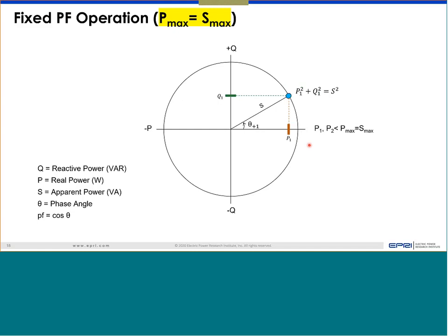If a further command comes, initially 0.97, now 0.92, then it has to go even lower, so real power has to go further down. So by having a power factor function, or a more aggressive power factor function, you can impact the active power generation. This might be important.